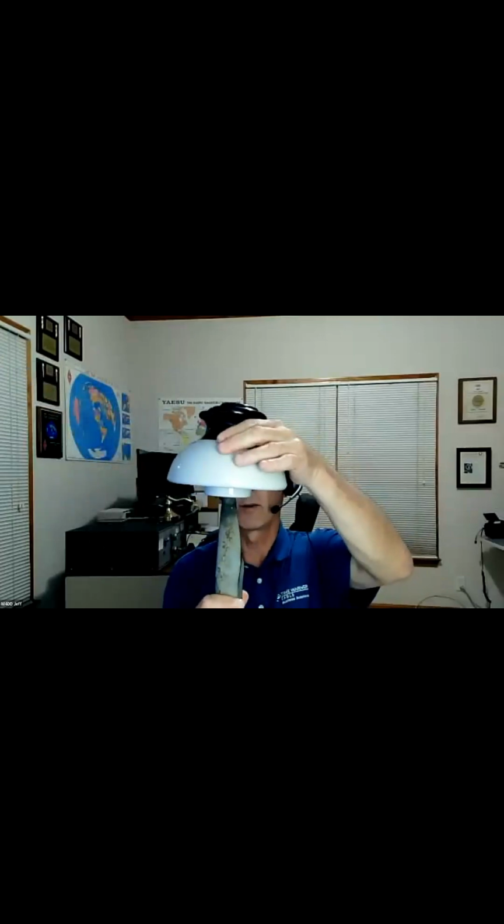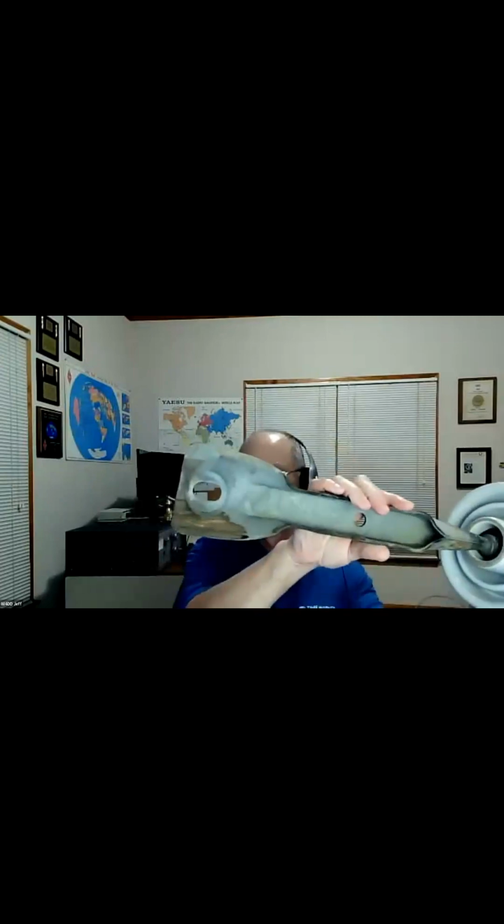Here's an example of what the pin looks like. The pin screws in the bottom, and that's what keeps it on the pole. And then there's 2 holes, if you can see both those holes, that hold this pin on the pole. And another source of potential noise is the bolts that go through this pin. Over a period of time, like years, 20, 30 years, the pole shrinks, the pin gets loose on the pole, and there'll be arcing between the pin and the bolts, especially if there's a little tension either way on this pin. So there's all kinds of things that can go wrong.